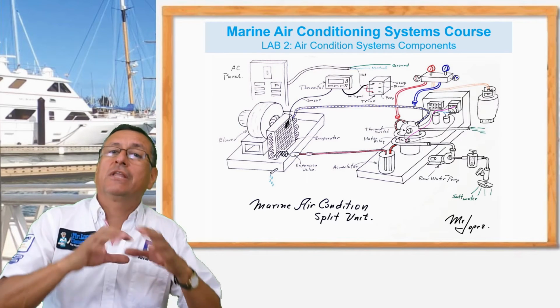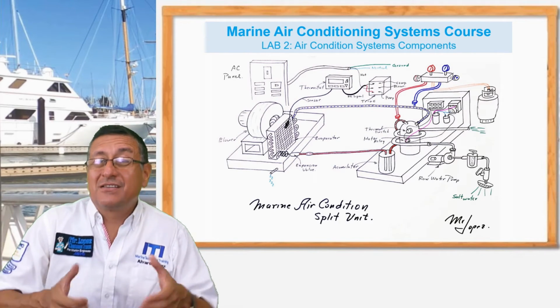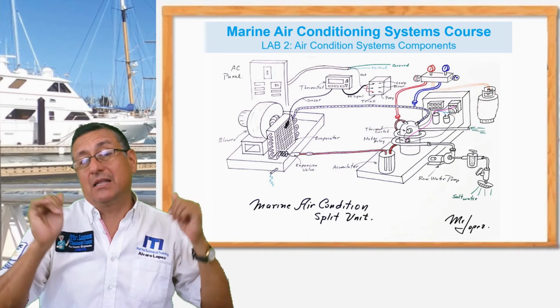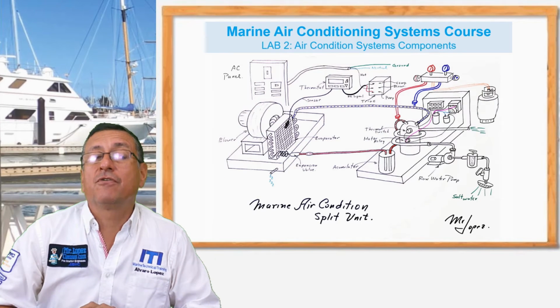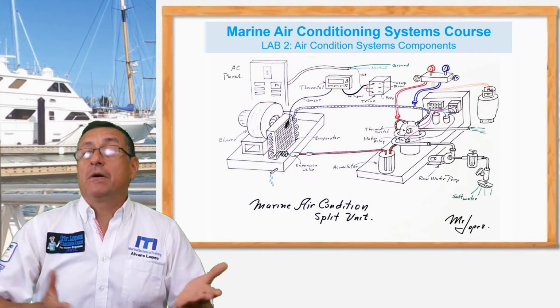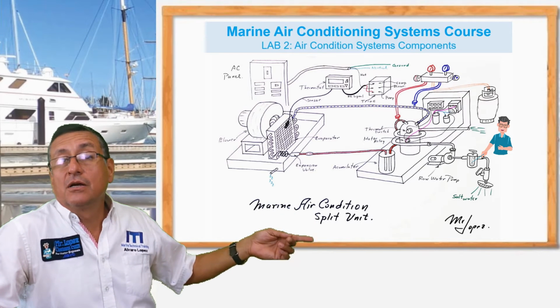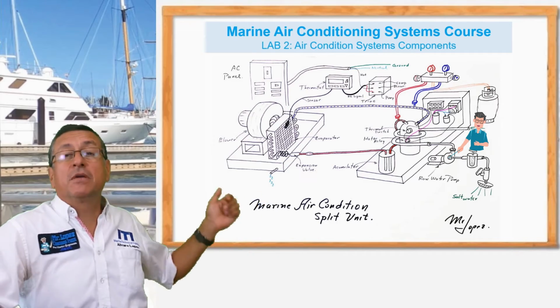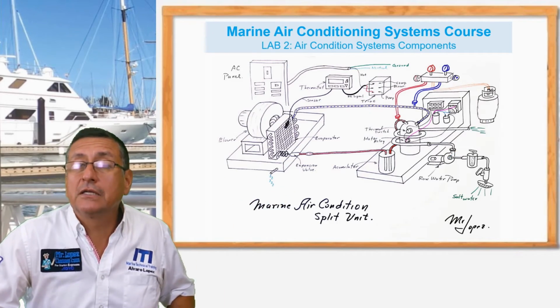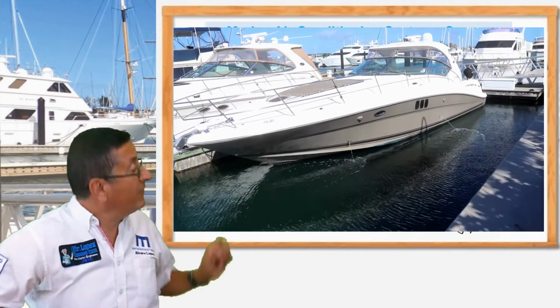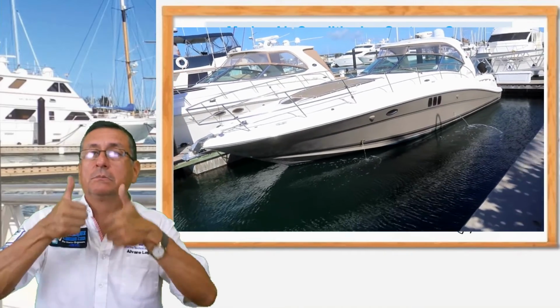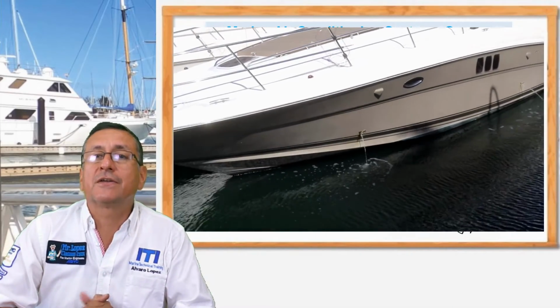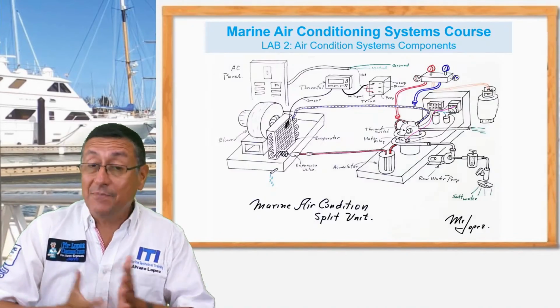For that reason, the coil in the condenser, the temperature increases and the system stops suddenly for high temperature. You have a problem on the sea strainer, or on the sea cock, or on the raw water pump, or the system is blocked, clogged. You need to solve the problem and verify that the flow of water is good, and right now the system is ready. That's the process.